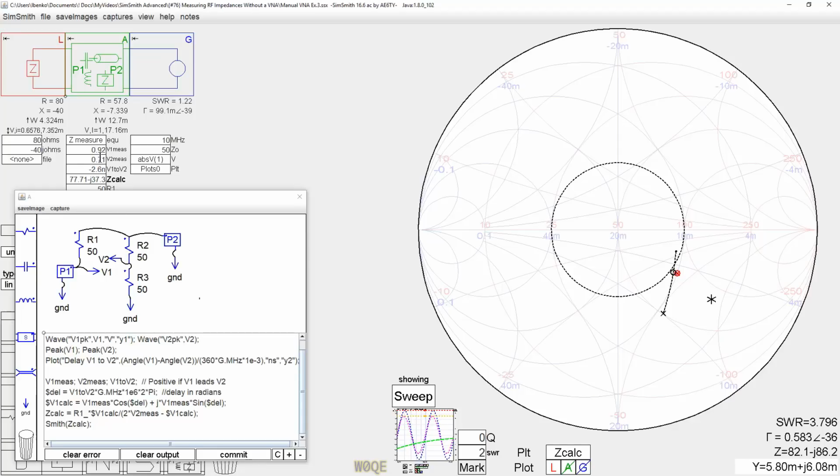I didn't exercise a huge amount of caution when I built this. I built these with some 1/4 watt resistors on a little solid piece of copper plane. And they were all 49.99 ohm 1/4 watt resistors. I did not use the little ground clips on the scope. I had a little piece of wire sticking up that was like a cradle that touched the ground part of the scope, and then the probe was right there. And I made the 2 measurements.